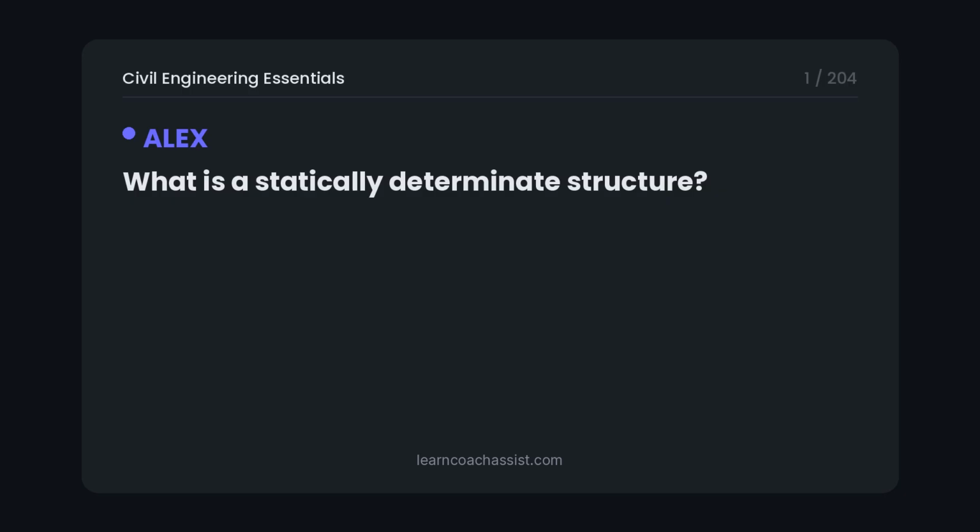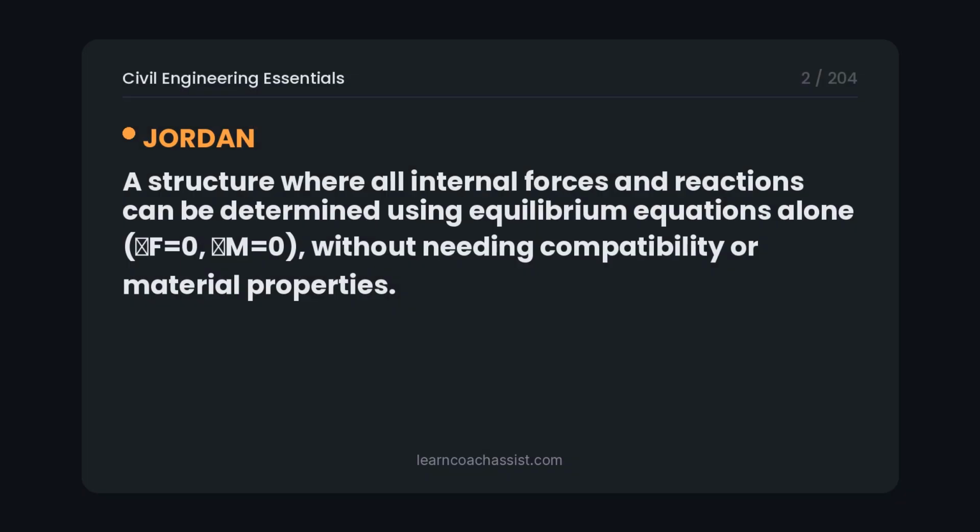What is a statically determinate structure? A structure where all internal forces and reactions can be determined using equilibrium equations alone, sigma F equals 0, sigma M equals 0, without needing compatibility or material properties.